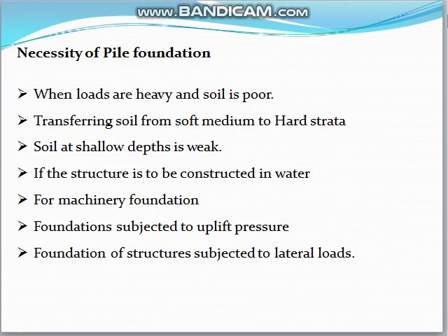I told you that in superstructure load, the total load will be carried by the soil beneath. That means the soil should have more bearing capacity. Depending upon the construction type, we check the soil bearing capacity, and based on that the type of foundation will be selected. In most cases, if you are not getting hard strata at shallow depth, we go for pile foundation.